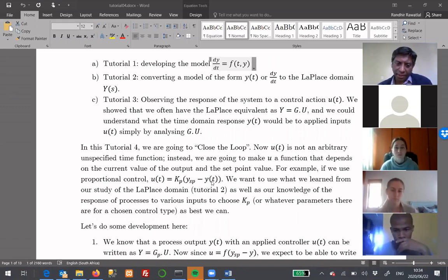So we currently have some temperature T in the reactor, and we wanted to reach some other temperature TSP. So the difference between those two, let's say our current temperature was 300 and we wanted to reach 400. So the difference of 100 should be proportional to the amount of control action we need to take. So for instance, if it's a high pressure steam, then we want to use steam in proportion to that difference.